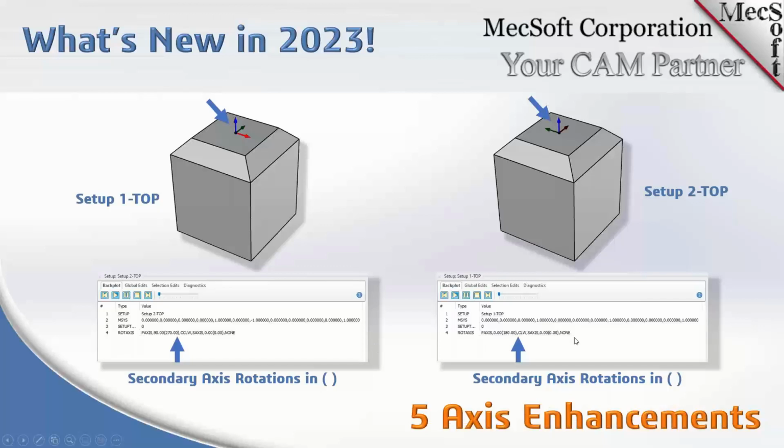If I can jump in here, Don. Sure. So basically in 5-axis, for any orientation of the tool, you have two possible solutions for the 5-axis angles of these rotary angles on the machine. So previously the system was actually computing both angles, but was only outputting the angle that the system thought was the appropriate angle.